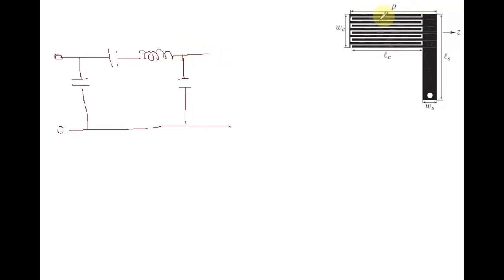So the first section is completed. Now this is connected again by this stub, and this stub is also shorted by this via, which is a conducting wire. So it makes the connection in between this stub line and the ground plane.